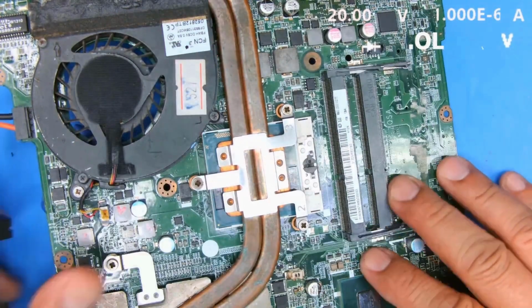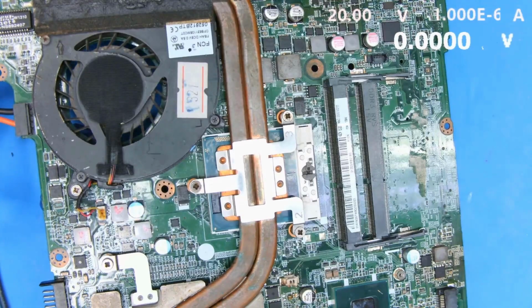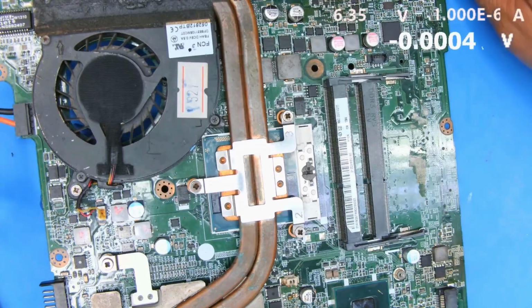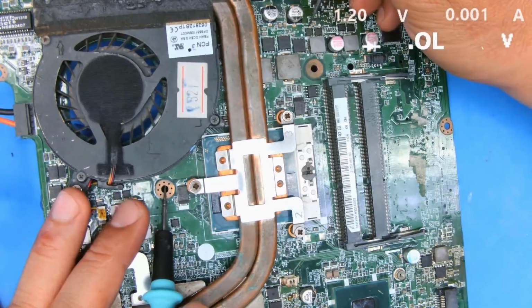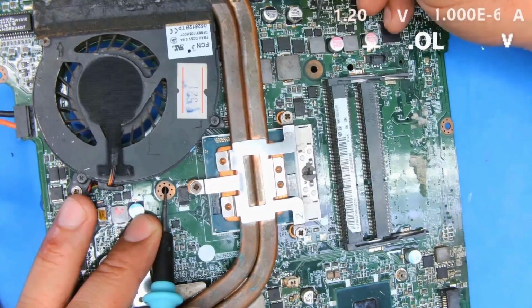Now, I'll switch to supplying power. First, set the meter to volts, then supply about 1.2 volts, as mentioned earlier. When supplying power to the positive side, how do we know which side is positive? In the case of the MOSFET we like, we can tell which side is positive because the positive side is the one where the diode reading is not 0. See, this one on the left is the source, which is ground. So we'll inject power here.